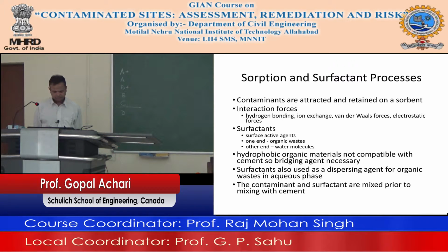Okay. So, hydrophobic organic materials are not compatible with cement. You may have to use some binding agents, because again the same thing: you have a hydrophobic material, you have a hydrophilic one, and you need something to tie the middle. Surfactants are also used as a dispersing agent for organic waste in the aqueous phase, as you saw in that video. It dispersed the little red molecules.